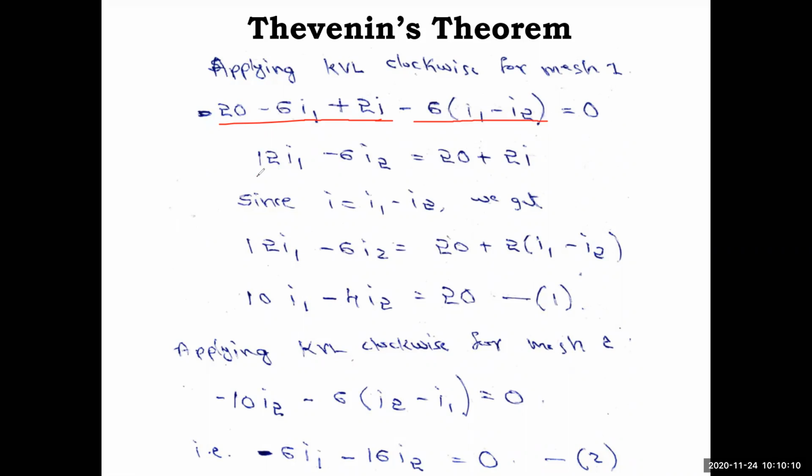So this is now minus 6 I1, minus 6 I1, minus 12 I1. Okay, and then plus 6 I2. So here we have taken the right side and rearranged the equation. You get 12 I1 minus 6 I2, and the left side you had as it is, 20 plus 2I. These are the two sources, right? One is dependent, one is independent, that we have grouped.